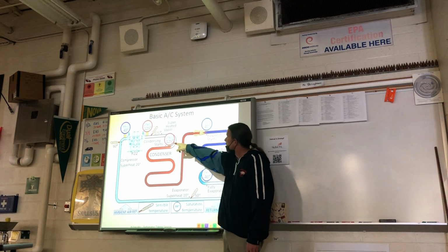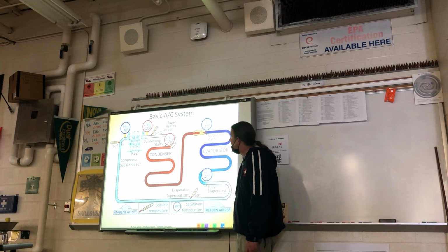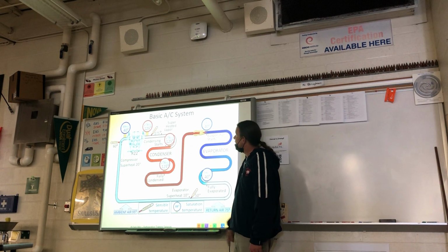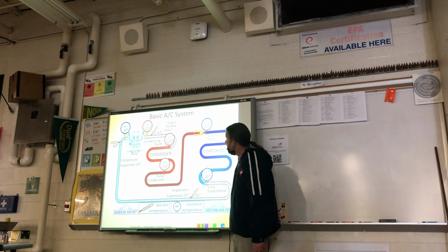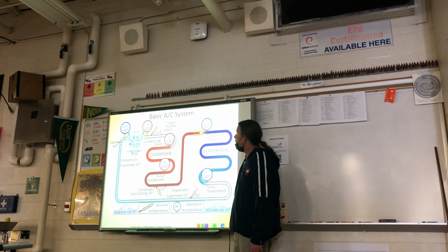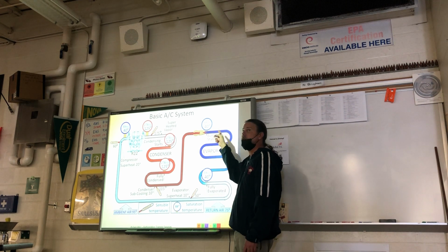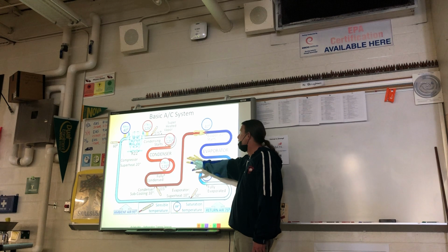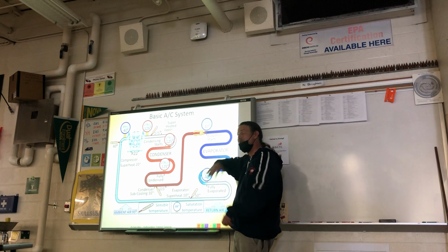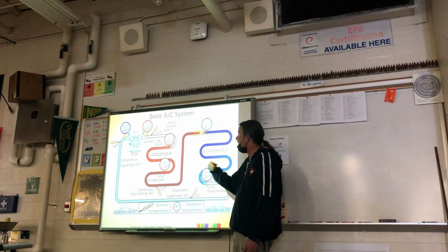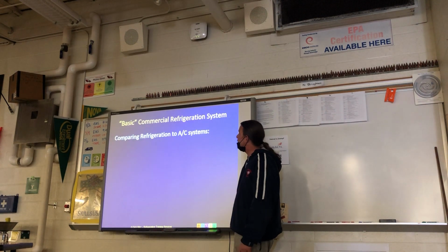And the first thing we've got to do is de-superheat that vapor to get it to condense. Once it's fully condensed, about 3/4 of the way through the condenser, then we can subcool that liquid back down to feed it again all the way back through. All right, that's more realistic to what you will see in the book instead of tanks. But it's all the same thing, except they're pipes, and we can run multiple pipes.